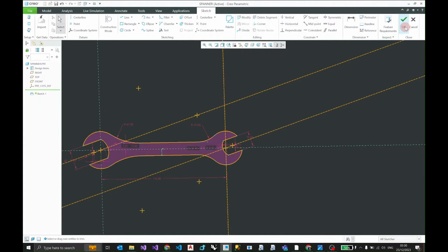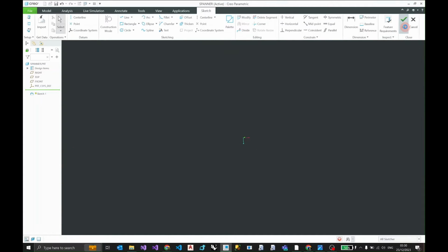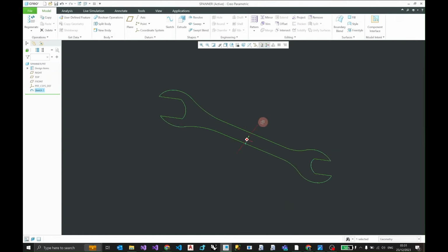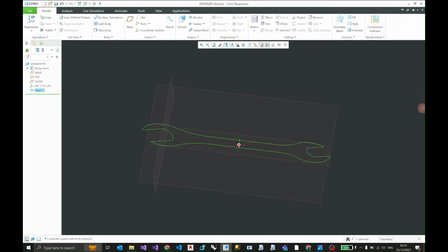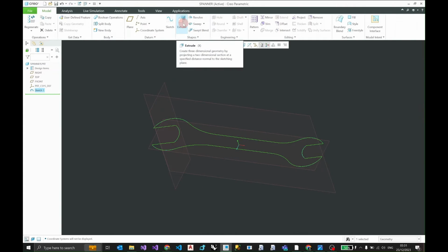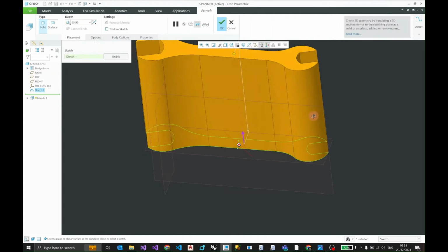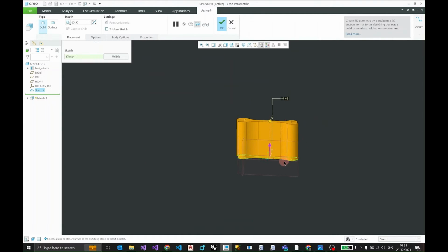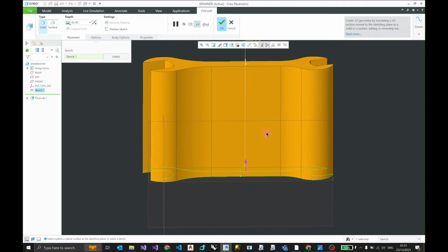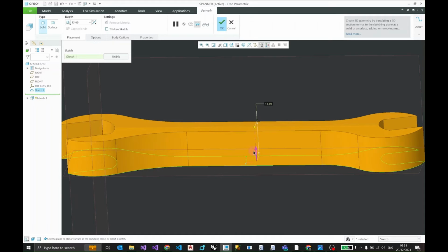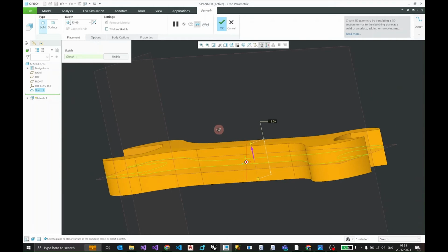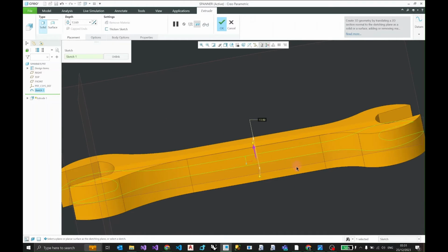Which means that now we can extrude this geometry. Extrude means we're gonna give it a thickness. So once it's selected, we're gonna go over here and select this extrude command, click it, and yeah. So now I'm gonna make this extrusion symmetrical. At the moment it's only extruding in one direction. What I need is a symmetric extrude in both directions.